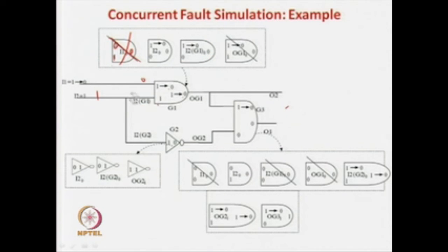So, whenever the faults are not over here, you are applying the change from 0 1 1 to 0 1, and here is the stuck at 0 fault. So, you can say that this is a change from this signal, and these signal values remain the same from the previous computation, and now this gate is having 1 0, from 1 to 0 you are going here. So, the answer is the same, the output is 0 and this is 1. So, these two gates become normal gates and the output stuck at 0 gate becomes similar. So, this gate also has to be dropped.